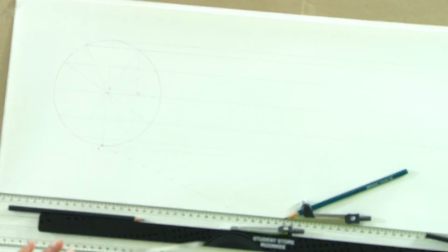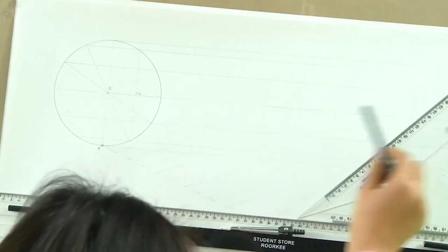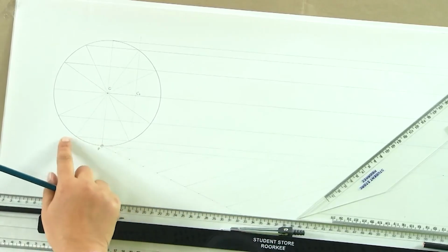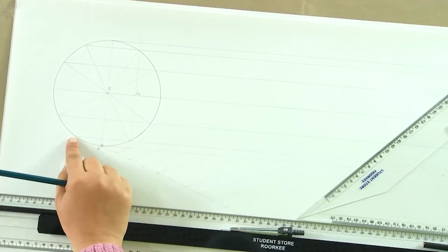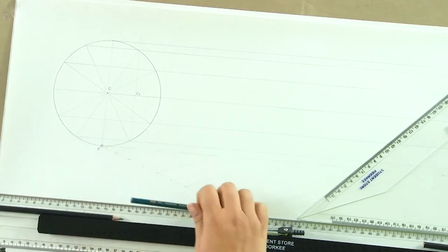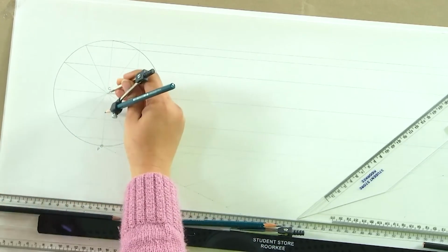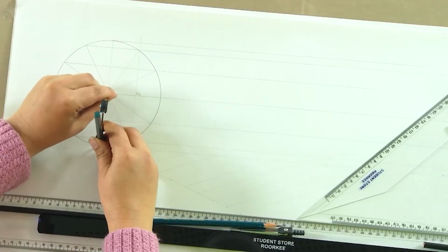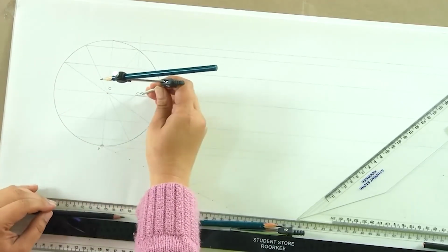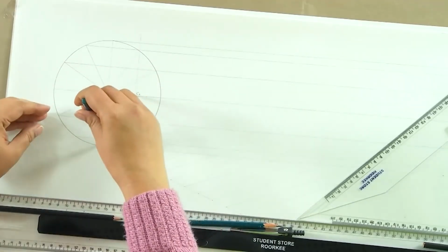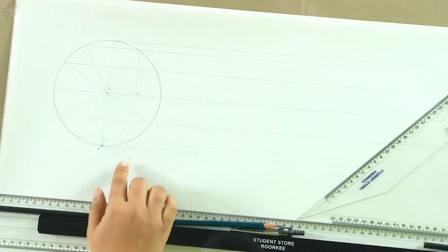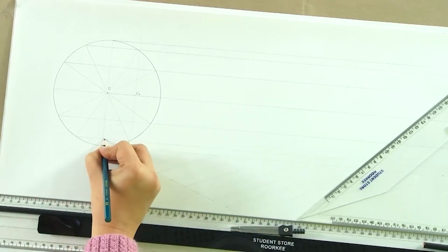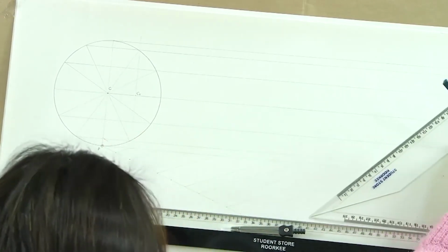Now, how much would that be? That is along this horizontal line. So, this P would have come to the position in horizontal, the position which is taken up by this next point. So, what we will do? We will keep our compass at 7 centimeters, which was the radius of the circle, and from C1 we will now mark a point in this line which is the second line. So, this is where the point P would have moved.